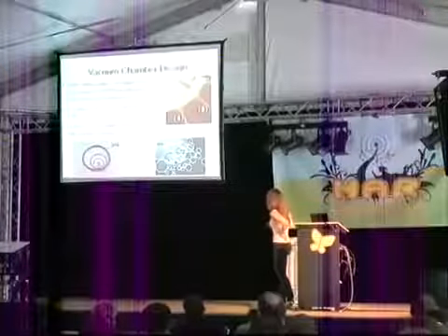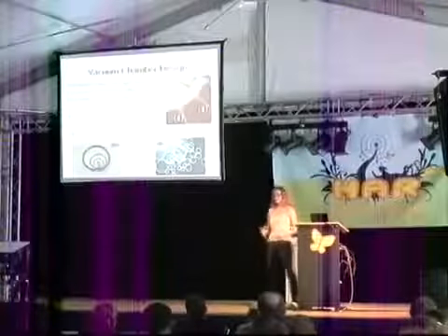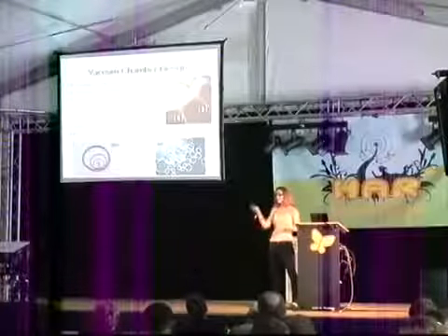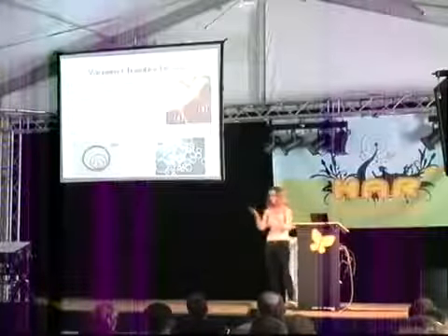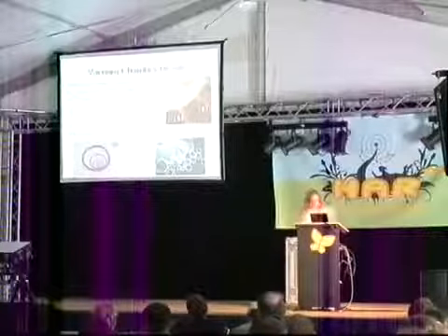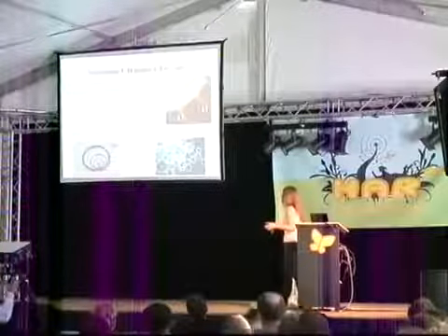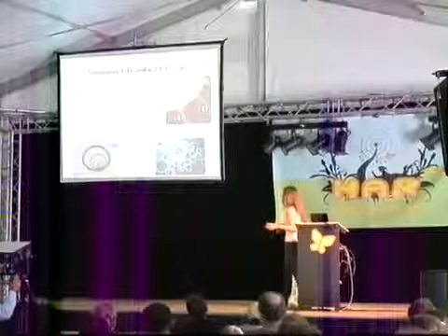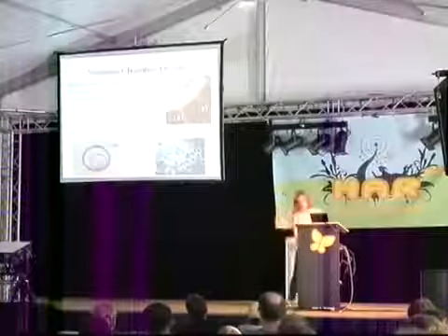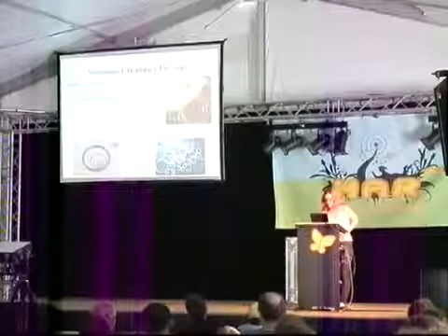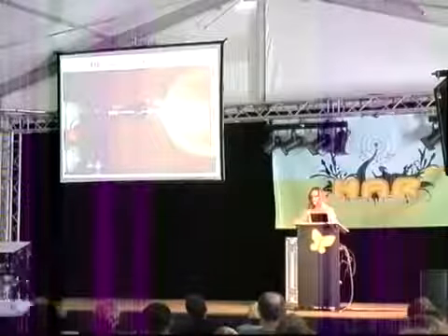I give that URL there. And that just shows things like, well, if I have an O-ring of this diameter with this cross-section, I want to make the width of the gland this much, the depth this much. So it's straightforward. Also, a brief aside on the type of O-rings you should use. Rubber O-rings, yes. Teflon O-rings, you don't want to use those. Those are for like rotating applications. Okay. So that was the end of the vacuum chamber design section.